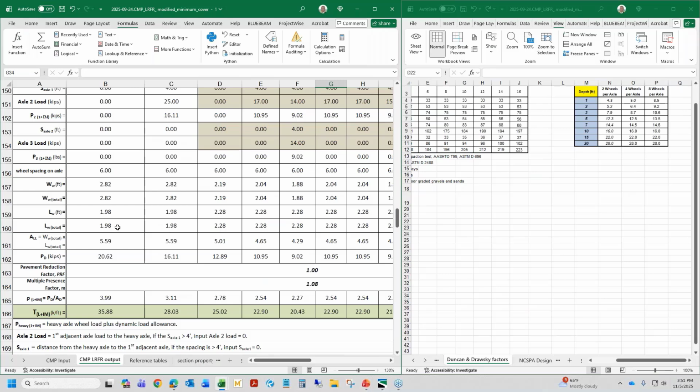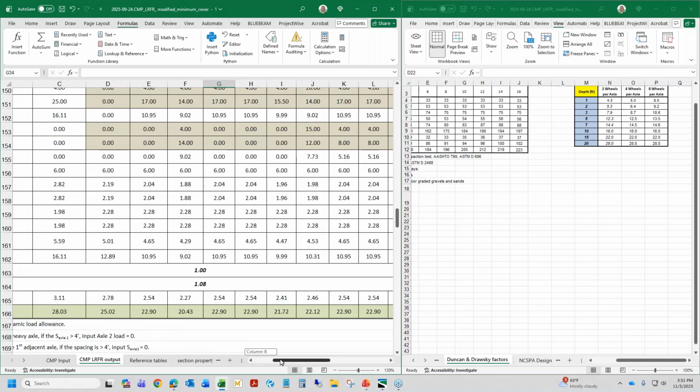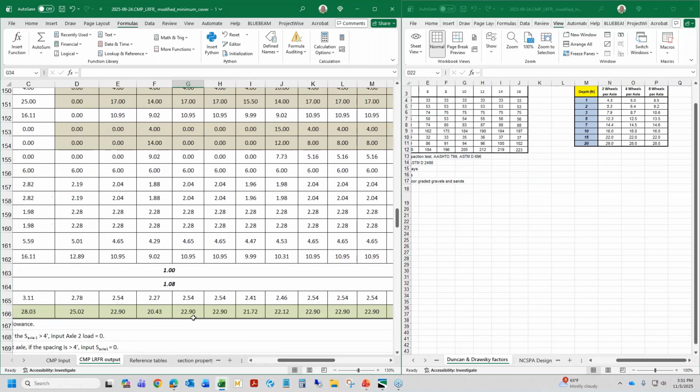And out of all those calculations, we end up with the thrust in the particular structure. That's the live load plus the impact. But again, if we look at these numbers, and keep in mind these are all factored values, they're around 20. We had 1 for the dead load, so we're talking something below 25. And if we remember, the capacity was 80. So again, we're at very low demand to resistance ratios when we're talking about thrust.